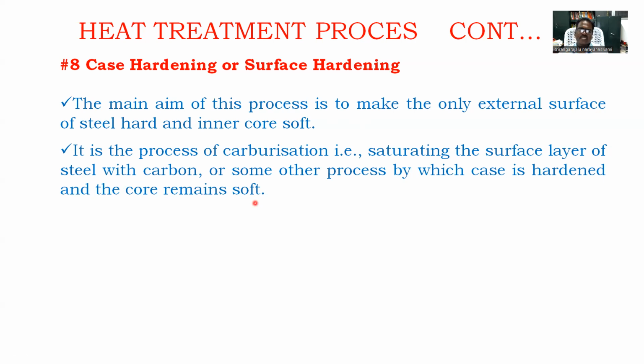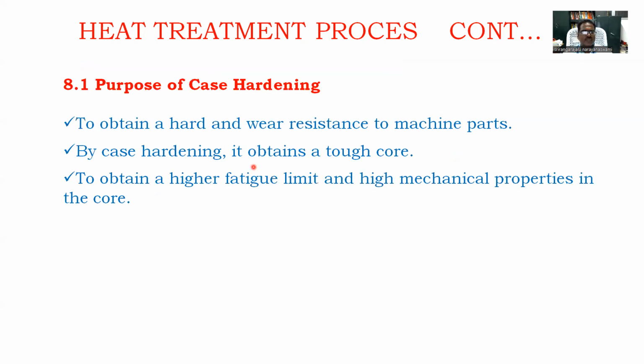This is for impact load. Wherever the impact load will act, for connecting rod, camshaft, crankshaft, and other parts, we can make a case hardening alone as required. An inner soft core is required, so at that time we can use case hardening.